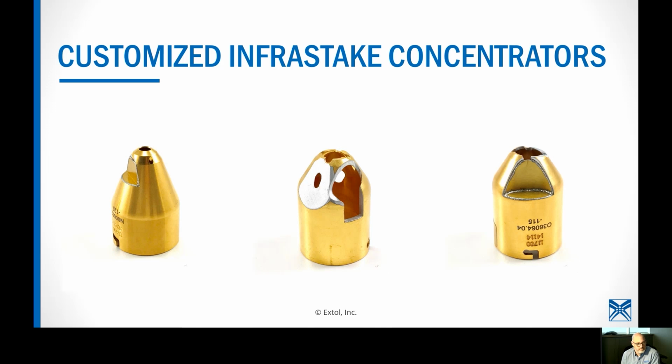Any danger with exposure to the light with a handheld staking technique? Handheld modules. Really not a good idea. The reason is InfraStake is really dependent on repeatability. The module needs to be oriented over top of the part at a specific angle, at a specific pressure every time. We've spent an hour talking about why it works really well. If you try to do that by hand, you take all of that out of the equation. We wouldn't recommend it. Have we seen customers do it? Yes, with marginal levels of success.